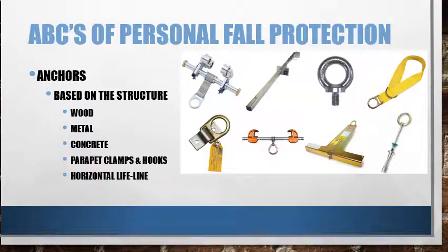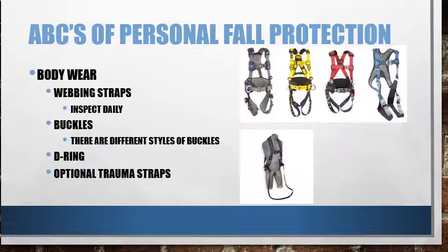So let's talk about anchors. You're to be anchored to the structure and choose the appropriate anchor based on the construction of that structure. There are different anchors for wood, metal, concrete. There are parapet clamps and hooks for the tops of buildings, and there are horizontal lifelines, which you drape across the building from one side to the other.